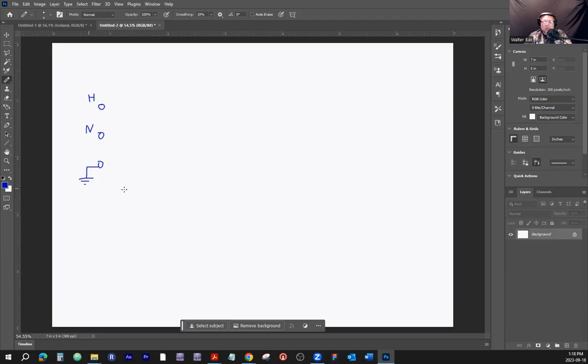If this terminal here is connected with a single uninterrupted wire, and it's going somewhere outside the building or wherever, or maybe inside the building, connected to a true ground with either a spike or a plate buried or directly connected to something that's labeled as a true ground, then we call that thing grounded, this terminal.